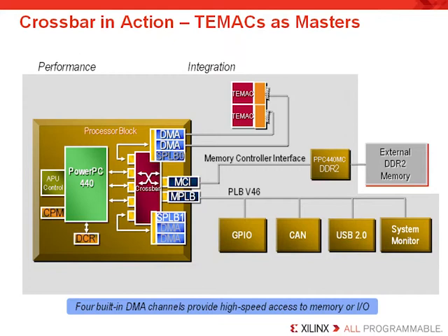Adding a TEMAC in the base system builder will result in the TEMAC being attached to the PLB bus. In other words, the base system builder defaults to building the TEMAC as a peripheral on the bus rather than directly connecting it to a DMA port.